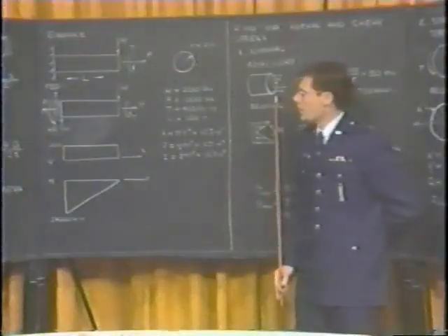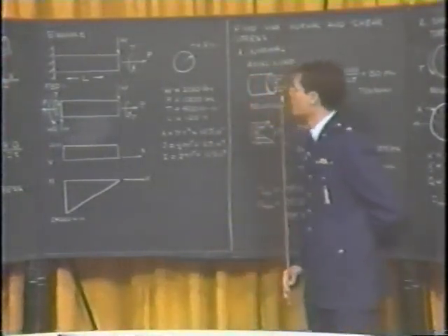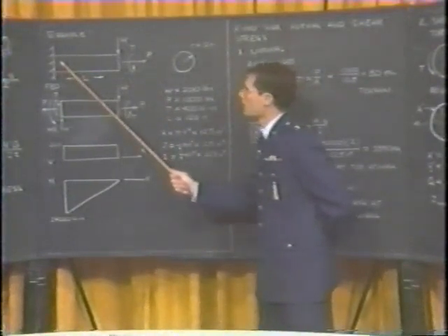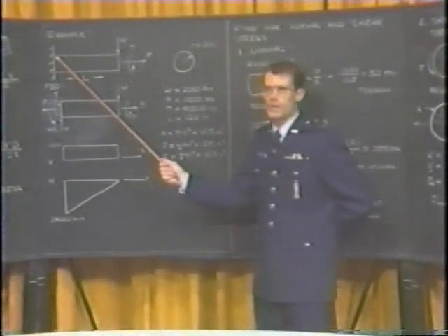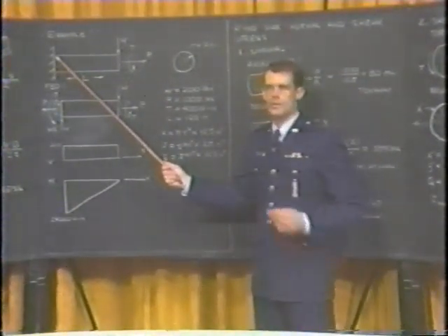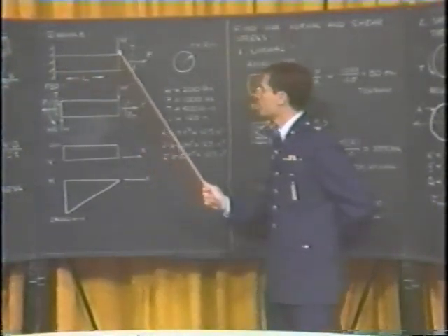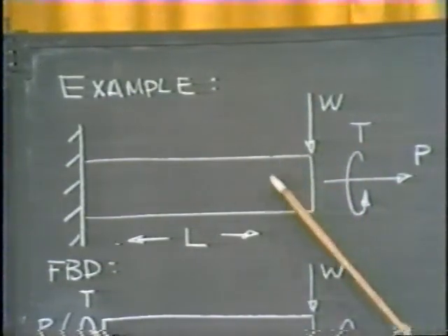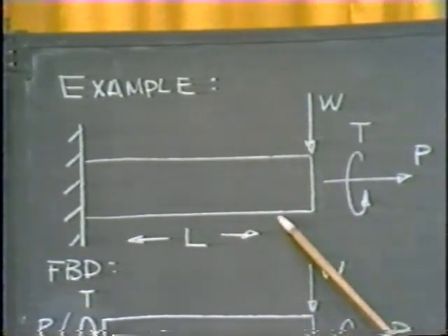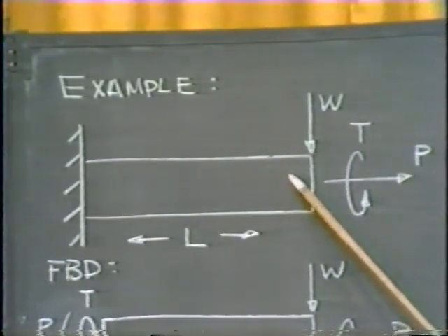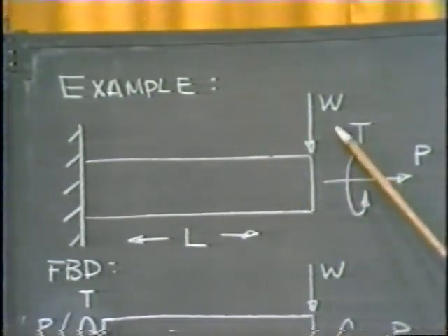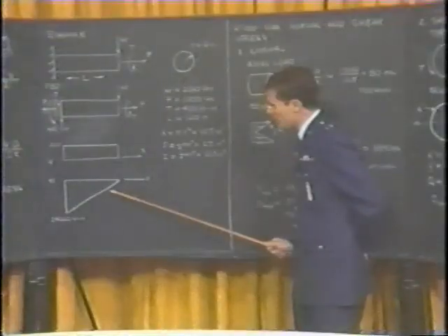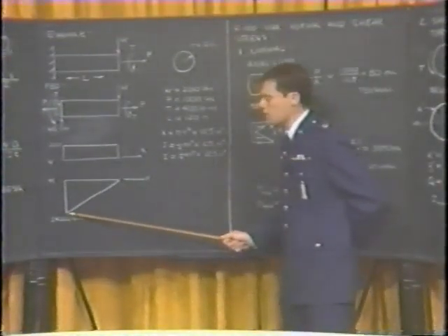With a little thought in mind, we might realize that the maximum normal stress may occur up here on the top corner of the beam. This is due to two facts. We know that the bending load will provide a normal stress that will reach a maximum at the top and the bottom surface, and that stress will also vary with the bending moment diagram. You recall our bending moment diagram down below. The maximum bending moment occurs clear back at the wall.